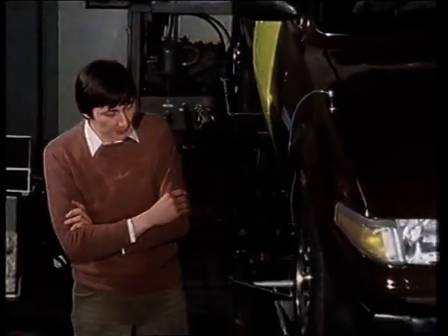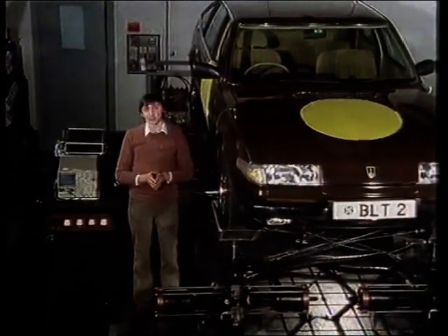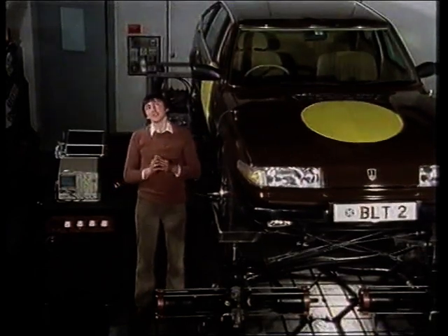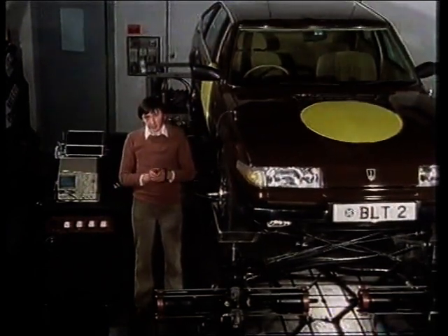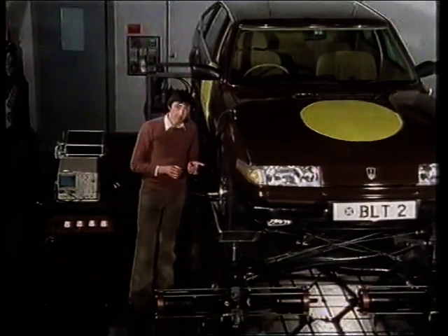Let's try the same sort of experiment with the two cars. We're going to apply a sinusoidal input displacement here of constant amplitude but steadily increasing frequency, up to about 10 hertz. That's rather like driving over the test track that we saw earlier at steadily increasing speed. Remember, this is the more lightly damped car. Being lightly damped, the transmissibility curve is quite peaked at resonance, as you'd expect.